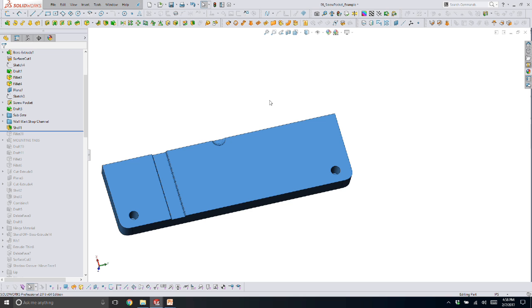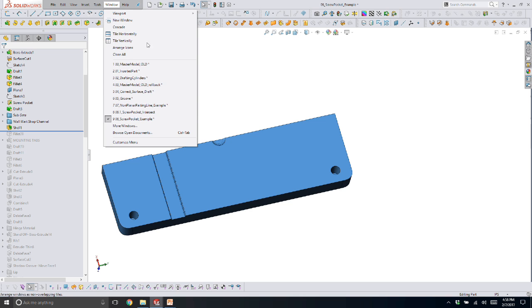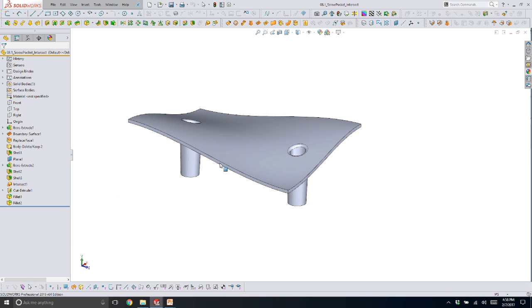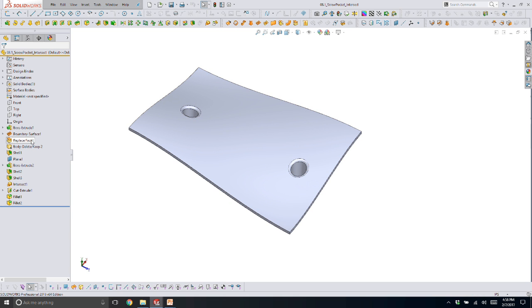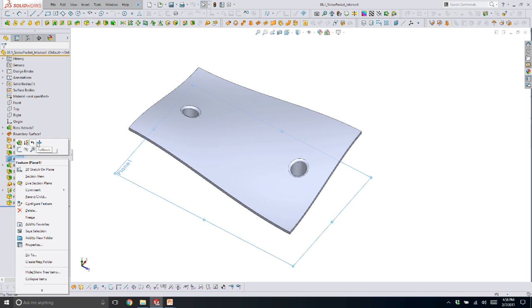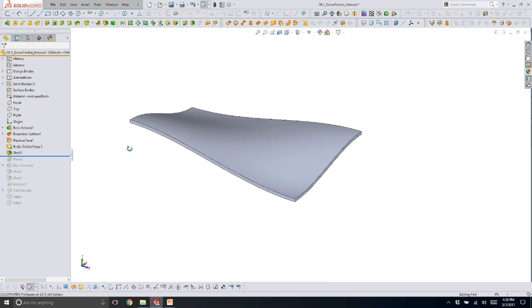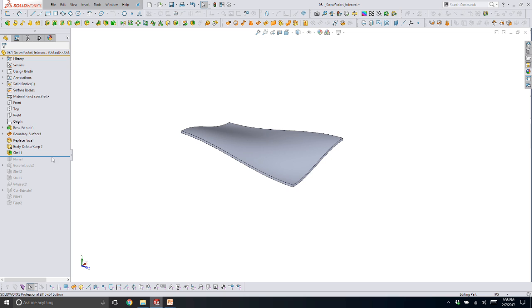If the part's already shelled, you can't do that. Plan B, which is a little more work, but we're going to do it with the intersect tool. So here this part's shelled. Now, I know you might be saying he's got the shell feature, why not roll? For the sake of this example, let's ignore that. I'm actually going to model the interior volume of the pocket as an extrude, because I can't cut. I don't have any geometry there to cut before the shell.